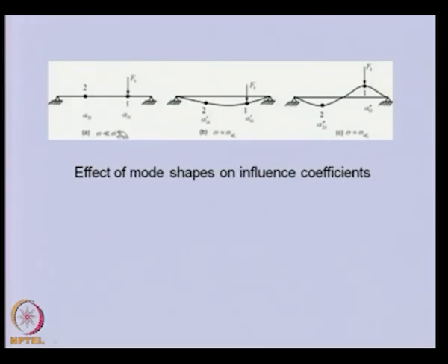This is valid when we are operating the rotor much below its critical speed. If we are near the first critical speed, for a simply supported rotor, we expect the shaft to have a deformation like a half sine wave.